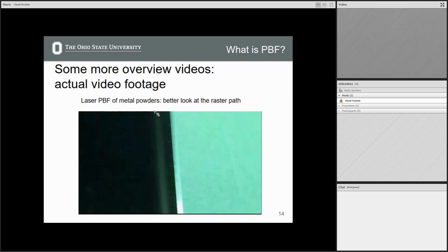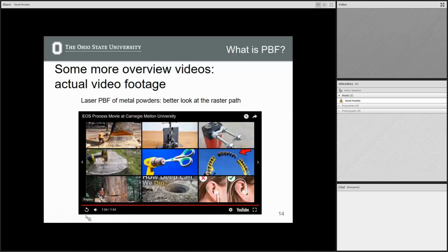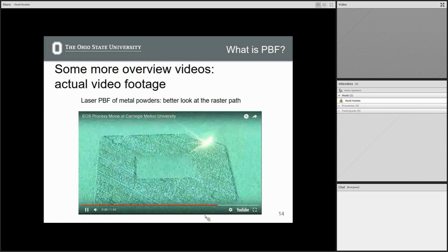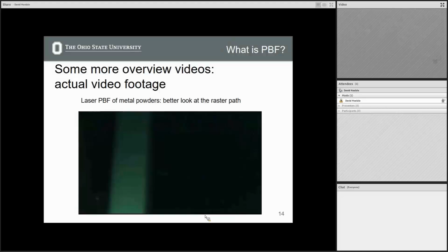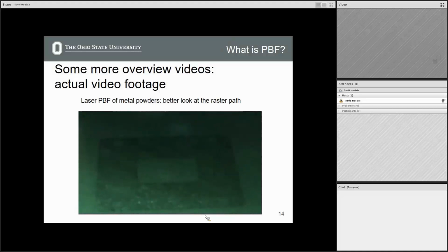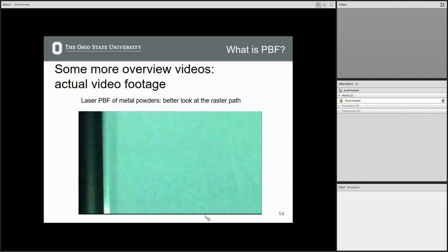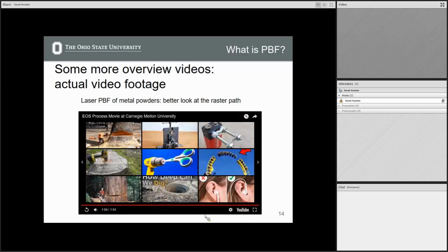Let me replay that again. Just watch, it's very fast, right? The laser moves incredibly fast, but it goes and circumscribes the entire part. What it's trying to do is improve the surface finish at each layer, because that's what you're going to ultimately see. Everything in the middle, you're not going to see once you build this up. If you have a nice surface finish, it does that last little move, almost faster than you can see it happen.